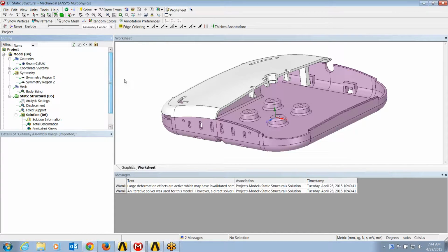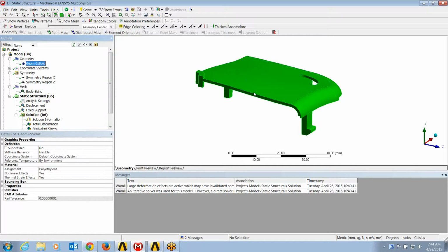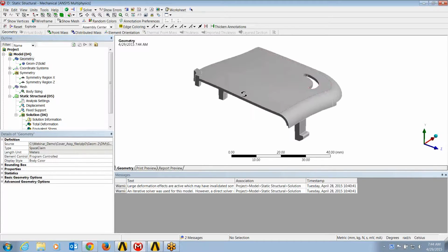So what I have is perhaps the approach that many of you are using out there to simulate these kinds of designs. We've taken that top cover and we've cut it into 4 parts because it's pretty much symmetric about the 2 vertical planes there. And we might start with a geometry model like this. From our assembly process, we know that this post right here has to move about 1 inch, or a millimeter and a half, backwards as it slides into that.